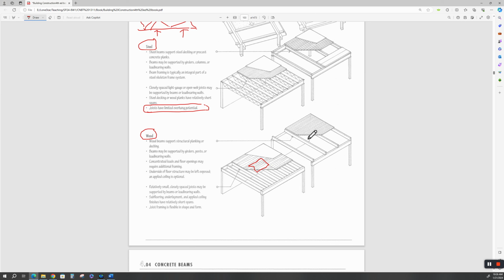He's talking about structural planking. Now this is just like tongue and groove flooring, and you can treat this as a diaphragm, but there's a lot more nailing involved, a lot more gluing, and I would suggest you also use a good glue like liquid nails in your design because it'll keep the bounce out. Because we all know this wood is not uniform.